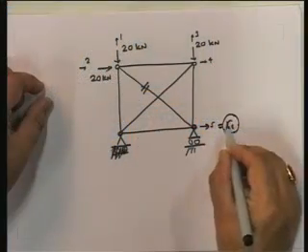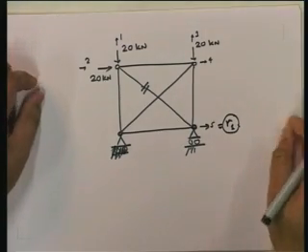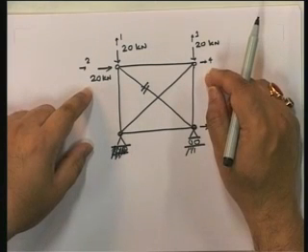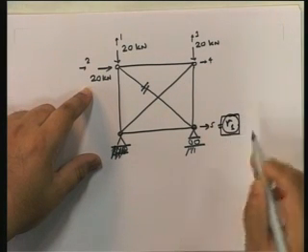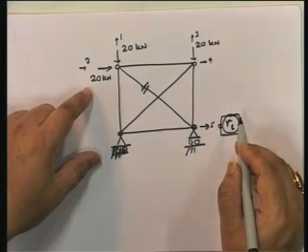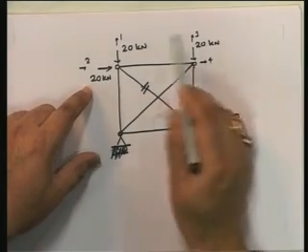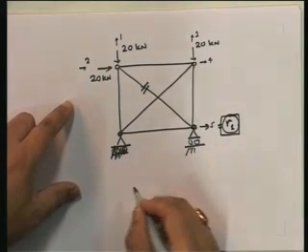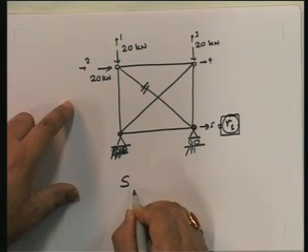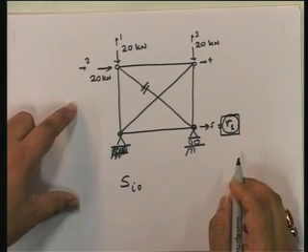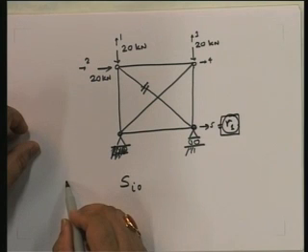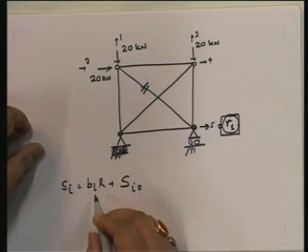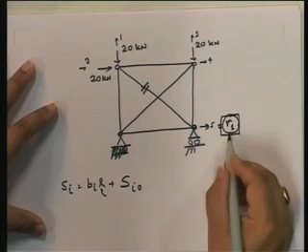So if this is my only degree of freedom that I'm interested in, understand that these then become actually not joint loads, although technically they are joint loads. But in this particular case, since I'm only interested in finding this out, I'm going to consider these do not come as members, and so I'm going to solve these separately, and I'm going to say that these are going to give me my SI0. Do you understand that point? Remember, I had said that you could solve it that SI is equal to BI into R plus SI0. In this particular case, R is the only one corresponding to this.